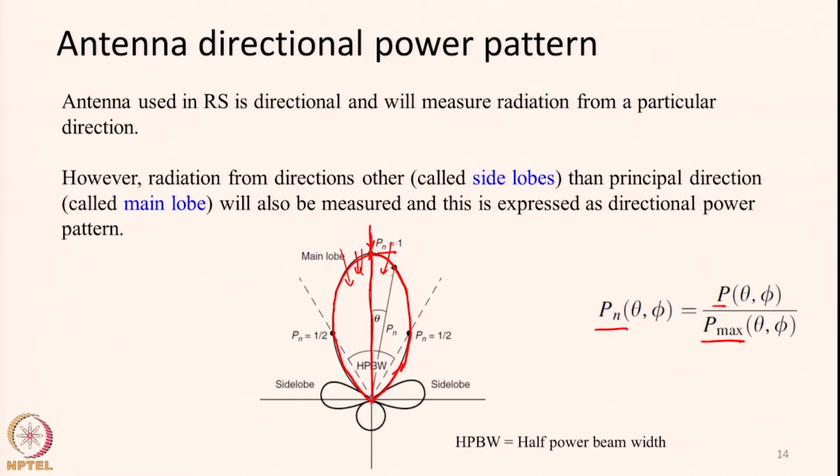Each antenna may have its own lobe pattern. Some antenna may be extremely directional, some antenna may not be as directional as we need, and so on. Okay. So, it depends on the directionality of the antenna. If the antenna is highly directional, then it may collect all the power coming in from only one particular direction, avoiding all other directions. These are the side lobes. So, even some energy coming in through these directions may enter the antenna in other directions apart from this specified one. Okay. So, essentially each antenna collects energy in the form of a lobe, basically we call it a lobe,